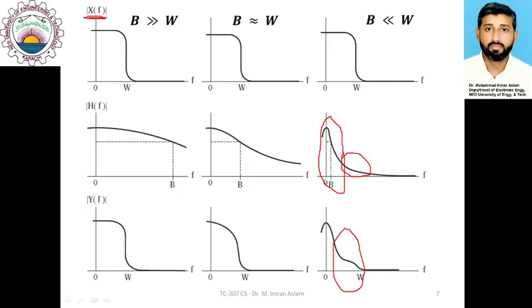And you can see that the spectrum of the output signal is significantly different from the spectrum of the input signal. Or if you look in the time domain, you would see that the shape of the waveform you would be getting at the output side would be significantly distorted, and you would not be able to recover the information that you intend to transmit from the input side.